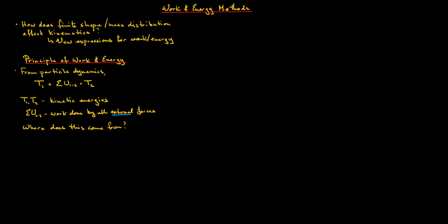So, let's turn our attention to the principle of work and energy. This was likely introduced to you in your study of particle dynamics. What it states is that T1 plus the sum of U going from 1 to 2 is equal to T2, where T1 and T2 are kinetic energies, and U is the work done by all external forces between points 1 and 2.